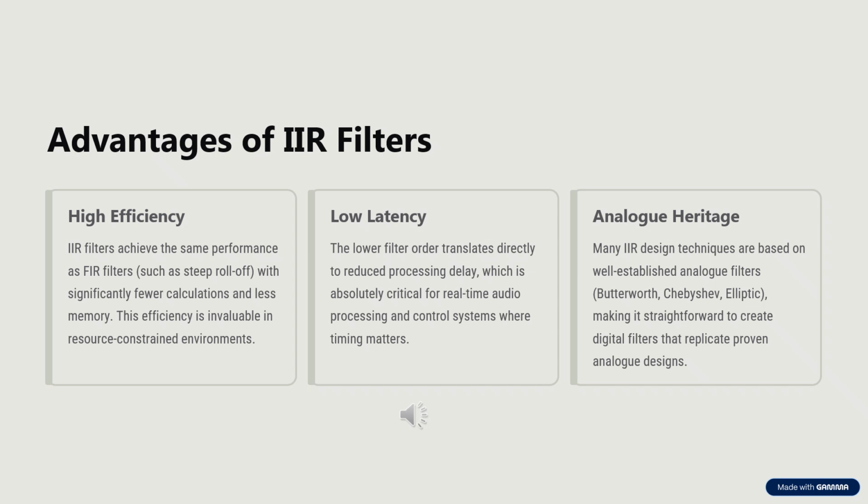It is the great advantage of the feedback loop that we can efficiently get the output without much computational cost, unlike the FIR filters that will require more coefficients to do the same job, because there is no feedback loop there and we have to rely only on the inputs that we have given.